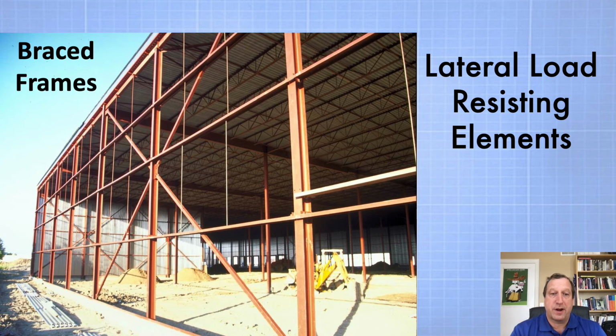The X brace that you're looking at is actually rather thin if you look at the scale of this building. This is about an 8.5 meter tall industrial warehouse. Those X braces are picking up a fair amount of load, and yet they're so efficient because they're in pure tension that they can be relatively small.